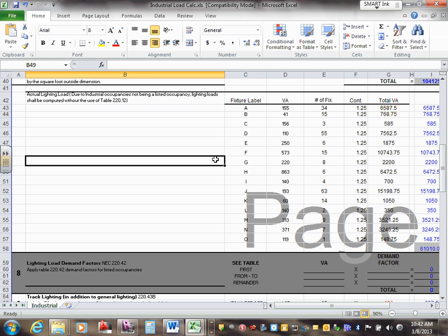So if you came up with anything less than 4,000 amp for the switchgear, you did something wrong. The switchgear will be 4,000 amp, the main. The rest are going to be slightly different, but the main is going to be 4,000 amp. Done. Okay, is this enough, guys, to get you running with the load calculation? Yes? Okay. Let me give you 10 minutes, and I'm going to just mention one more thing about Microsoft Project. I'll let you work on your stuff.